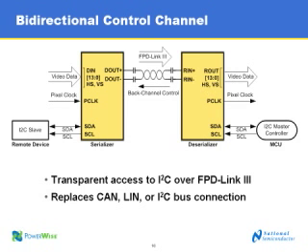In this case, instead of doing that, they put it on the I2C at the deserializer. The bidirectional control channel basically acts as a bus, and it gets received at the serializer, then sent to the slave. So you've effectively got the ECU at the deserializer side controlling, say, your camera imager through this. And it's basically transparent with the caveat that we can't break the laws of physics. There is a distance physically on that wire, so that imposes some constraints on the I2C operation.